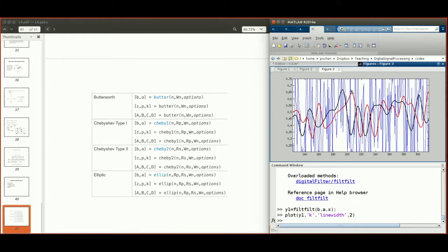So this waveform has been shifted to this waveform. Right, there's a delay, a group delay basically, right? But the black line has zero phase in it. So with respect to the original input signal, the black line has no phase distortion. All the changes are caused by the amplitude of the filter, right?